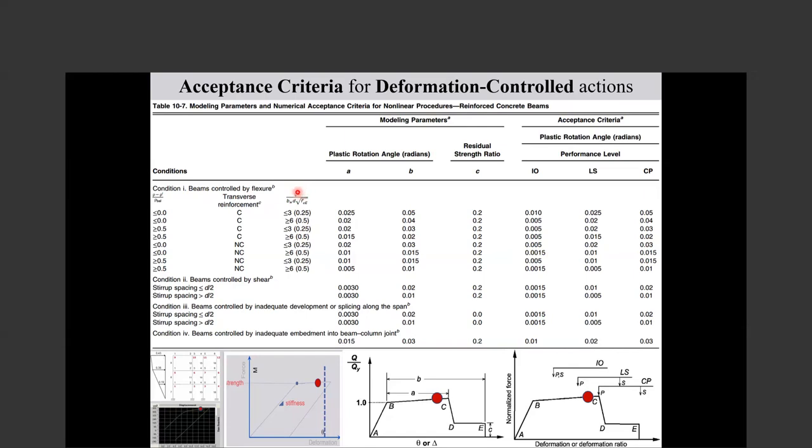The best option is that for each load combination, you change the properties of the hinges based on the V for that load, which is a little difficult. For each load combination, changing the properties of hinges is too much. So people usually use the worst case.